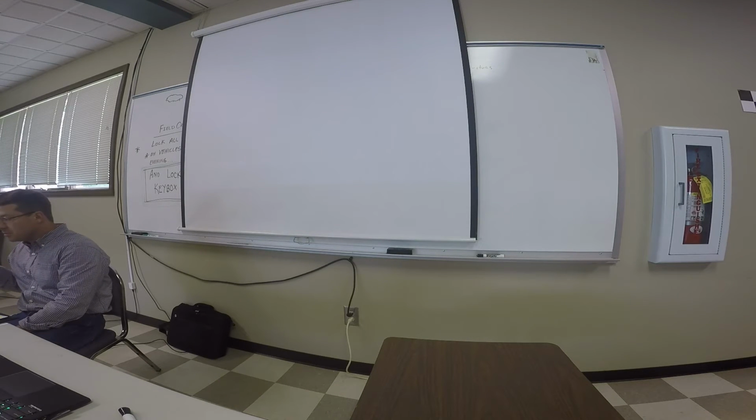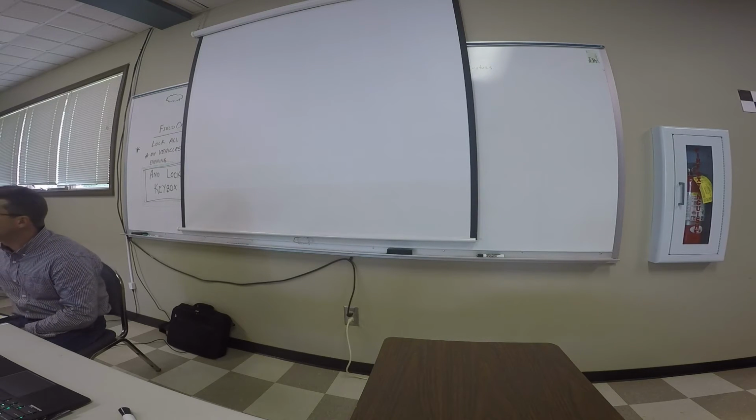All right, and when would you use a space? Double codes. If you want to do point of tangent, point of curve, that'd be just a space. Well, double coding, obviously, and then shooting your curves. We typically shoot 3 points on a curve: the PC, and then the point on the curve, which we don't actually call POC anymore. Carlson understands that once you begin a curve, it won't end it until you hit PT, and it'll do a best fit through those curves.